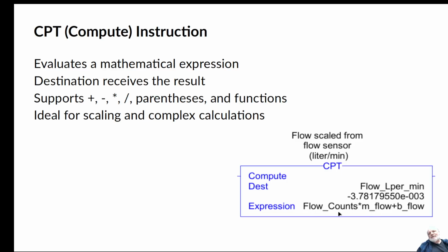So I have a flow count. This is my analog input coming from card 2, which is the 3rd slot. And then I have a scaling factor called my slope M, and then an intercept value. So this is my scaling factor, and this was the last calculation done on this compute statement.